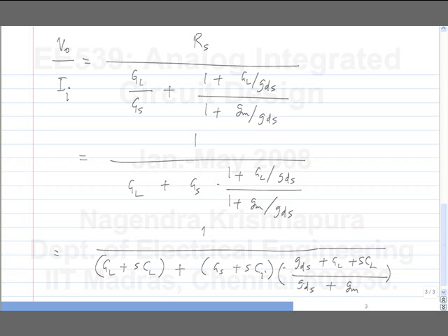Yeah, you can. Like I said the other day, if you use the frequency dependent gain in the Miller effect, the expressions will be exactly right. Now, if you use it from the DC gain, first of all, it's not hard to do the DC analysis, right? So once you do the DC analysis, you don't have to do it anymore. So it will be true only for DC. If you calculate the high frequency pole based on that expression, it will not be correct. So you can do it, that's the bottom line.